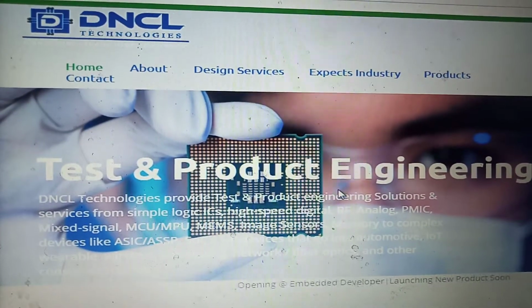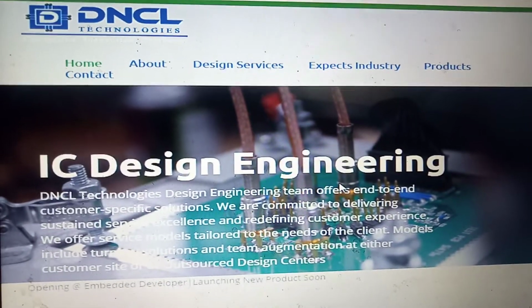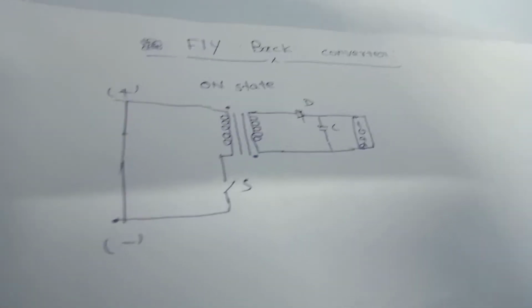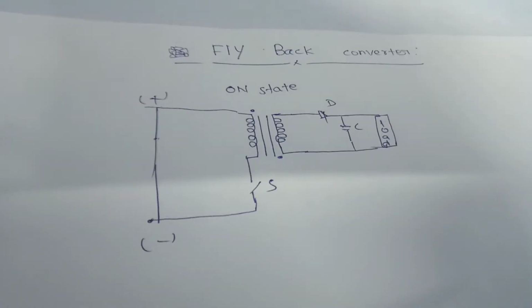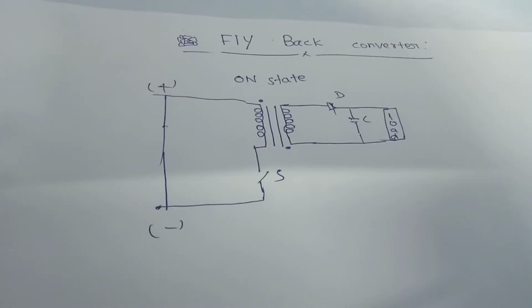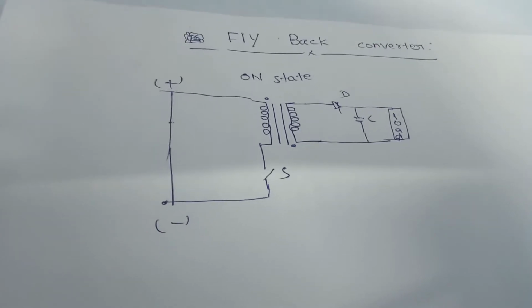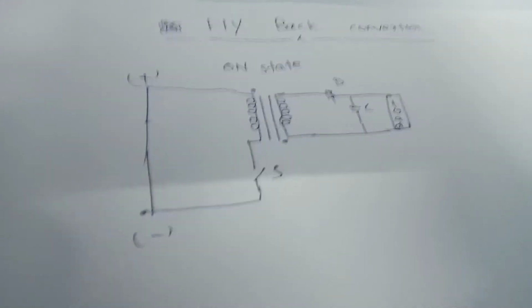So coming to today, we can discuss flyback topology. How it is working for flyback topology, we can explain in this section. This is the basic structure of flyback topology. Here we are using one switch, one pulse transformer, then a diode, a capacitor and a load. Here we are using DC input plus and minus. So how it is working, I can explain to you.